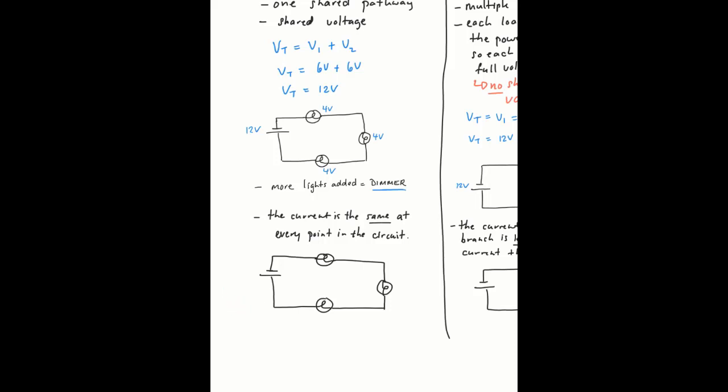And I would measure that using something called an ammeter. And you actually need to put the ammeter into the circuit. So you can put an ammeter there. You could do it over here at a separate time. I can measure over here, and I could measure over here. It doesn't matter what part of the wire. Make sure that your ammeters are added in series because you want to measure the current that's flowing through that wire. Okay, so it must be in the pathway. So you would take a connection, you'd break that wire there, and you put it on the other side of the ammeter. Okay.